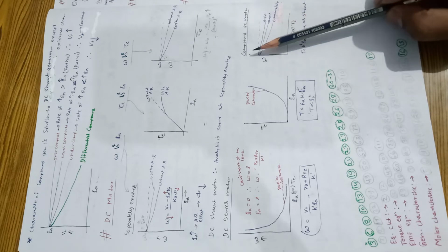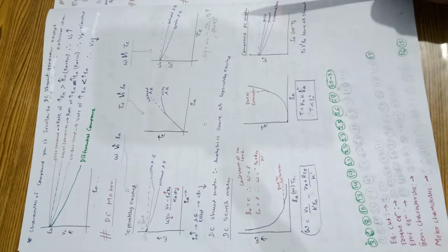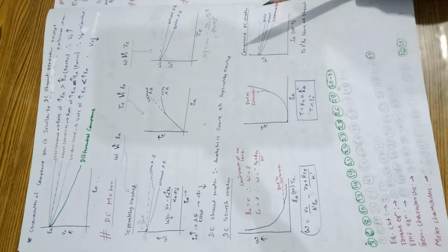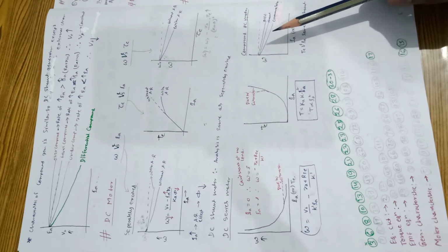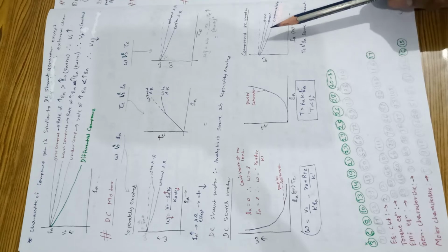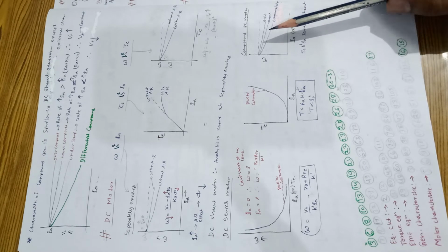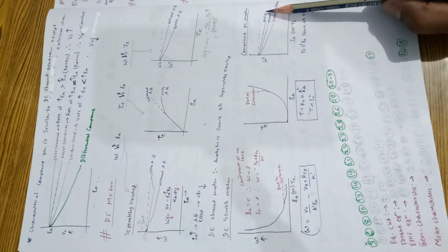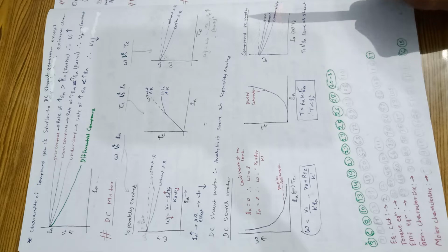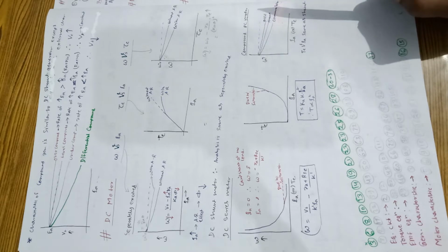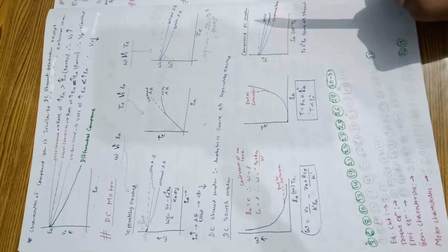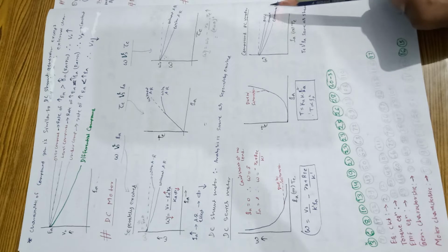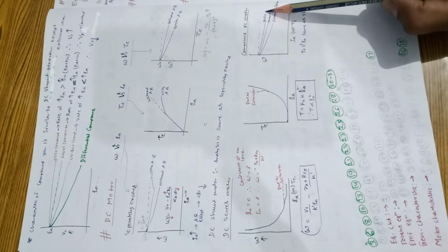Let us see this and complete this here only. According to the field, when we talk about the field flux, we know that field flux is minimum in case of a differential compound, because they are subtracted. In case of differential, phi SH minus phi SE, that's why we have the minimum flux there.